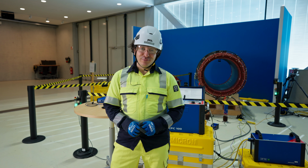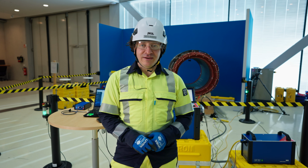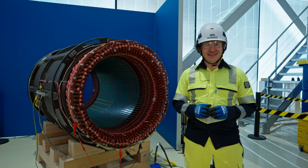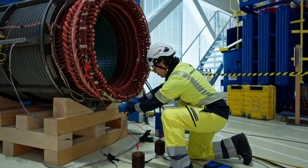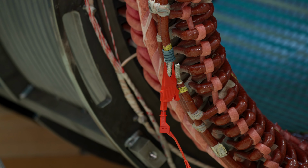Let me show you how to perform partial discharge measurements on our stator winding that we have prepared here in our training center. Partial discharge testing is one of the most sensitive methods to detect insulation defects in rotating machines, such as voids, delamination, slot discharges, or end winding problems.